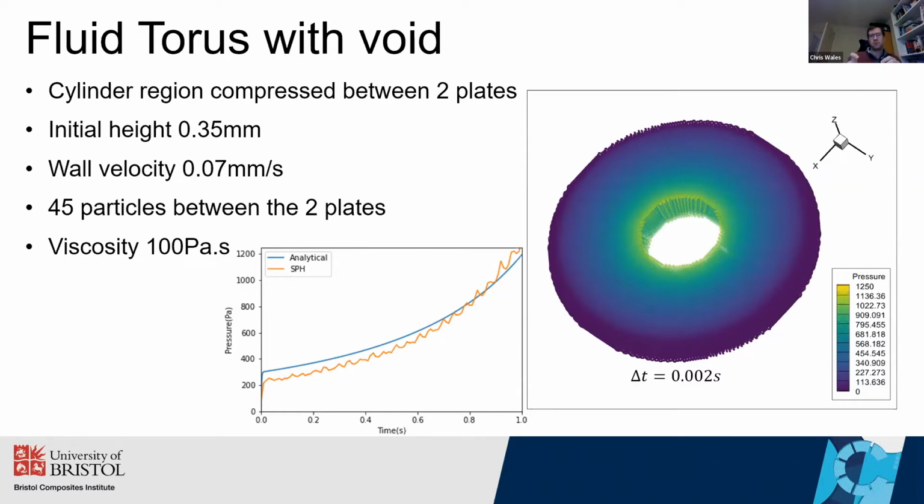And so this is related to how accurately we can map the volume ratio of the overlapped region in a gas cell by the SPH cell. And we had to introduce a small cutoff value at the minimum overlap region to stop areas of spurious gas regions being identified within the bulk volume fluid.